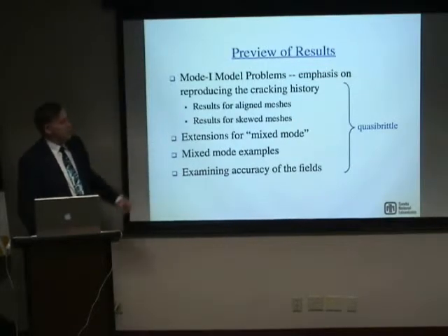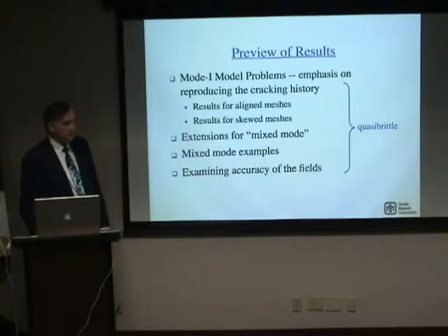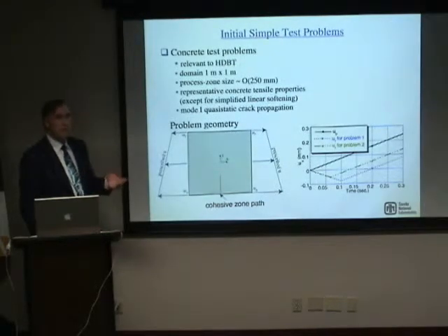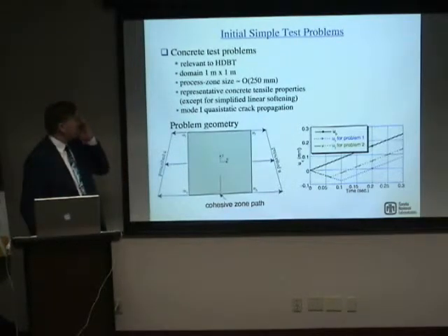Now, I would mention here that all the problems I'm presenting today are for a quasi-brittle idealization. That is, the material outside of the crack itself is treated as elastic, but we're going to have a cohesive crack that has a finite length. So the interest initially is to see if the enrichment will even work for the class of problems, as you asked earlier, and see if it will work for the class of problems that correspond to the analytical solution, and that would be a quasi-brittle type problem.